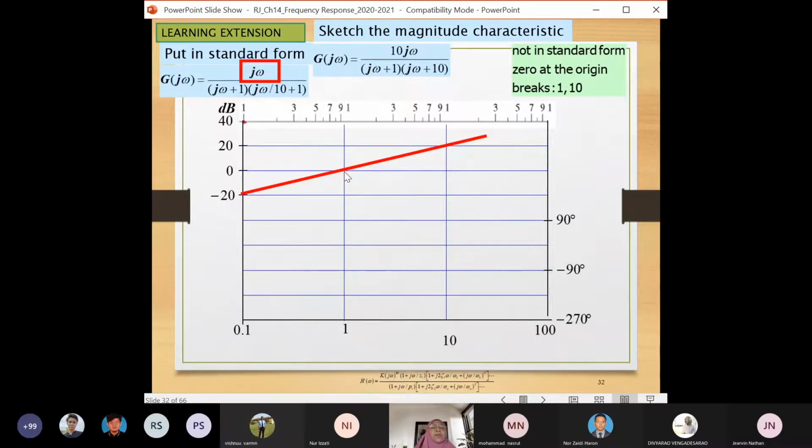Okay, here is the line running through the origin with a slope of 20 dB, which is obtained from the zeros equation, from the numerator of the transfer function. And then the phase for these zeros is going to be flat at positive 90 degrees.